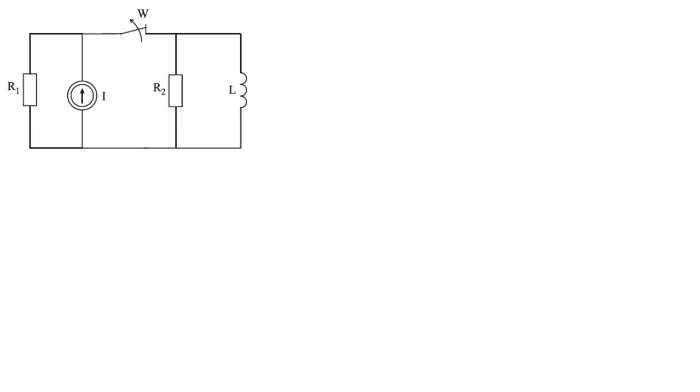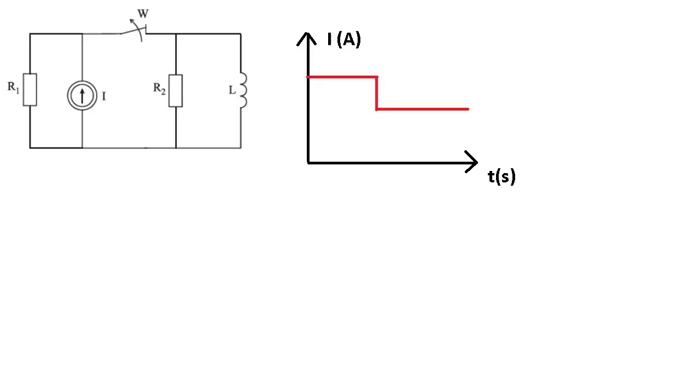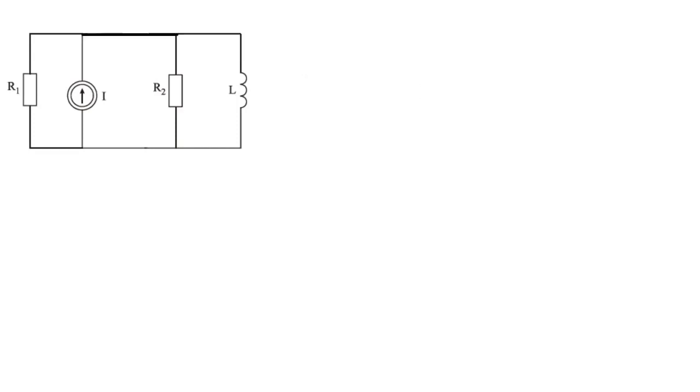I will calculate the transient response of current and voltage in the presented system using the classical method. In DC circuits, a change in voltage causes a step change in current only in purely resistive applications. If there is a coil or a capacitor in the circuit, the changes in voltage and current are no longer instant. The transient response of the circuit can be represented by a mathematical function, which I will calculate for the